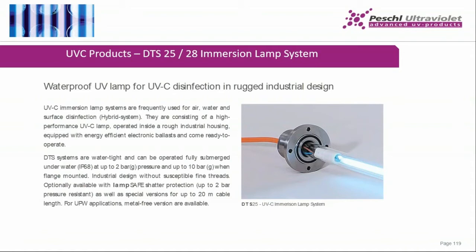to have them clean and safe from cross-contamination. You can also put it in a vessel, stainless steel please, because if you have plastic like PP, white or whatever, the material can be damaged by UV. So you have to take care, if you use UV, that the surface is UV resistant.